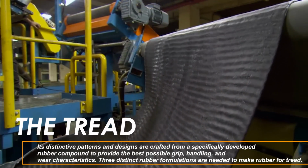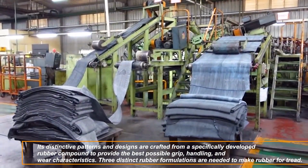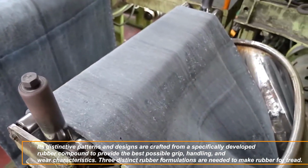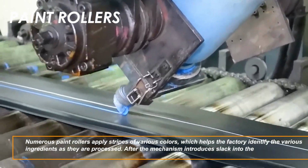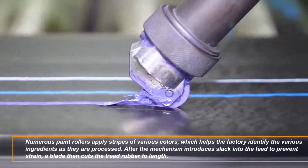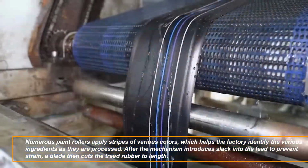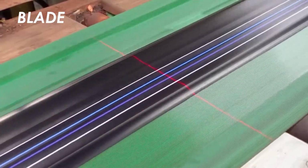The outermost portion of the tire that makes contact with the road is called the tread. Its distinctive patterns and designs are crafted from a specifically developed rubber compound to provide the best possible grip, handling, and wear characteristics. 3 distinct rubber formulations are needed to make rubber for tread. Extruders shape the 3 rubber streams, and a die then combines them into one. Numerous paint rollers apply stripes of various colors, which helps the factory identify the various ingredients as they are processed. After the mechanism introduces slack into the feed to prevent strain, a blade then cuts the tread rubber to length.